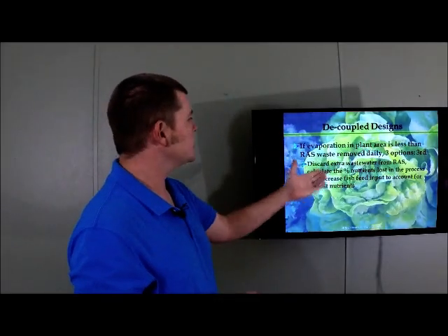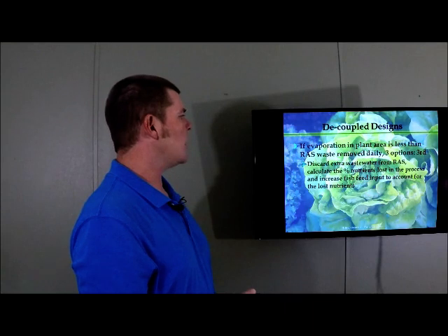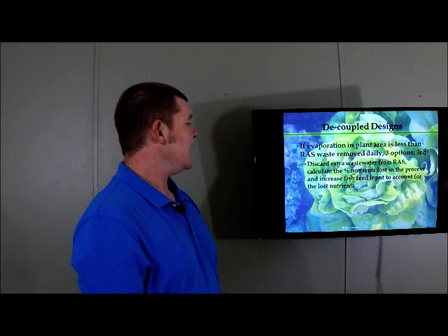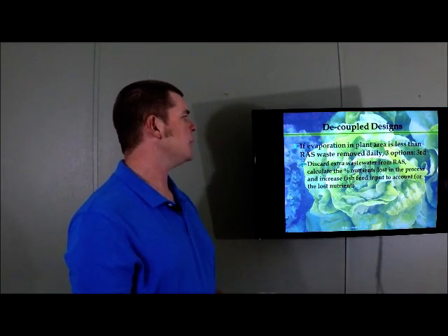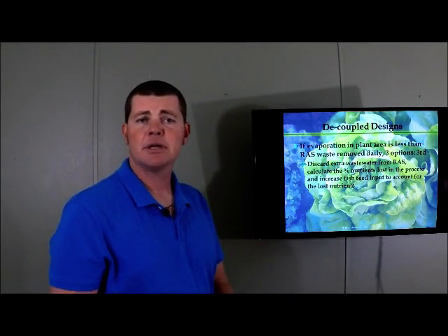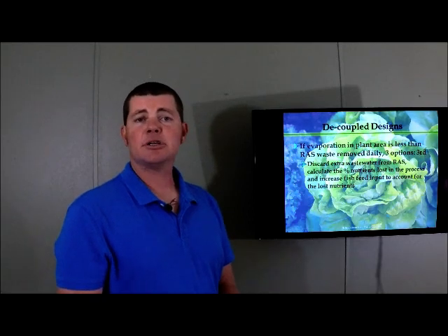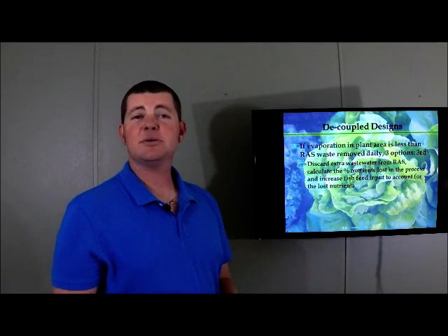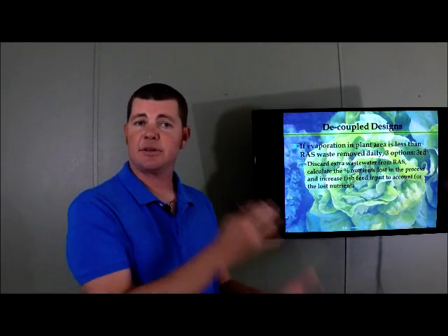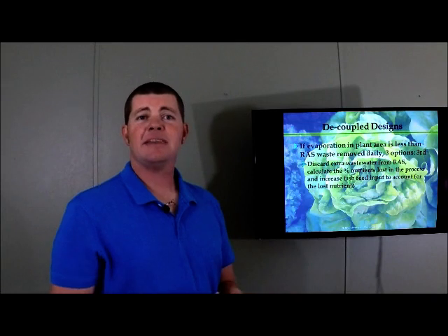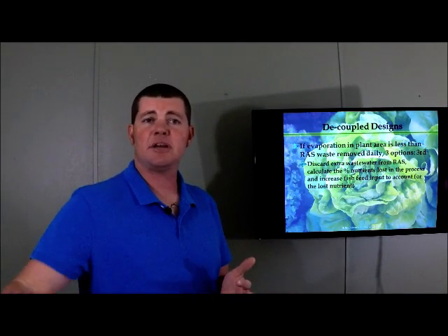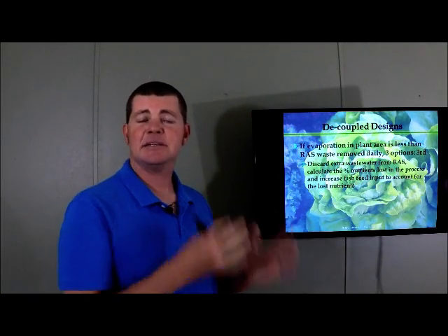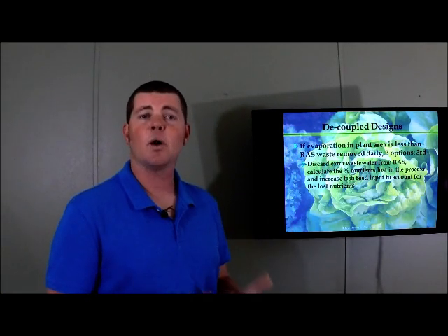And then the third option is we can discard the extra wastewater from the RAS, calculate the percent of nutrients lost in the process, and increase the fish feed input to account for the lost nutrients. Okay, so if we're discarding 20% of our nutrients because we can't fit them into the water, then what we can do is increase our feed input to the fish system by 20%. And that way, even though we're discarding 20% of the nutrients, because we've increased by 20%, the plant side is still balanced and still getting what it needs.